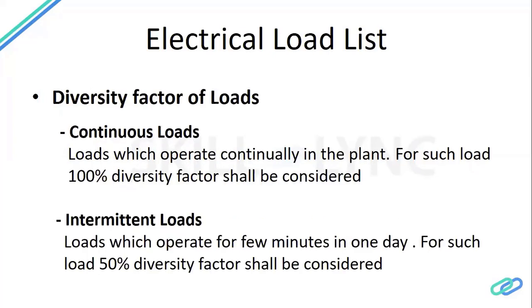Diversity factor of loads. What is the diversity factor? In the power plant, you have lots of equipment, but all are not running continuously. Some may be required once in a week, once in a month. So you will not consider everything at full load in the transformer. Otherwise, your transformer will be oversized. So for optimizing the transformer sizing, we use the diversity factor.